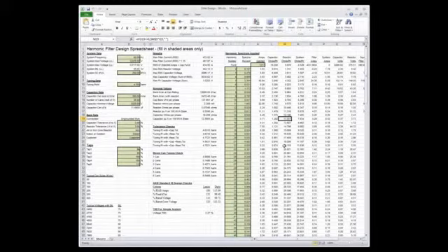Talking about the switches for the individual cans. My recommendation for the individual cans is that in all the filters that I've designed, there aren't switches on them. There are individual fuses. And my recommendation would be that for your filter applications, whether they're metal enclosed or outdoor stack rack, in either case you have individual fusing on each capacitor unit.